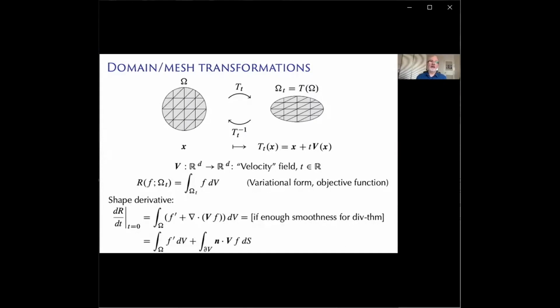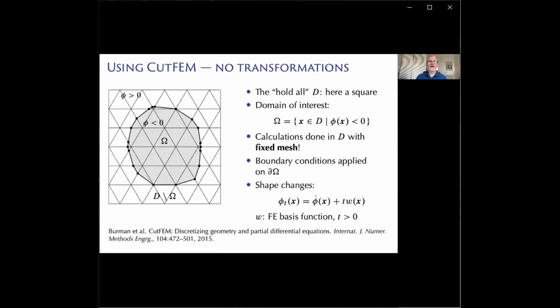The complication here is that the function f often is not smooth. For instance, when f is the integrand of the stiffness matrix in a finite element discretization, the use of the divergence theorem is not really justified. Thus, the use of the boundary formulations of shape derivatives in the context of finite element discretizations generates inaccurate gradient directions. Mesh deformations, however, are somewhat of a practical hassle, particularly in 3D.